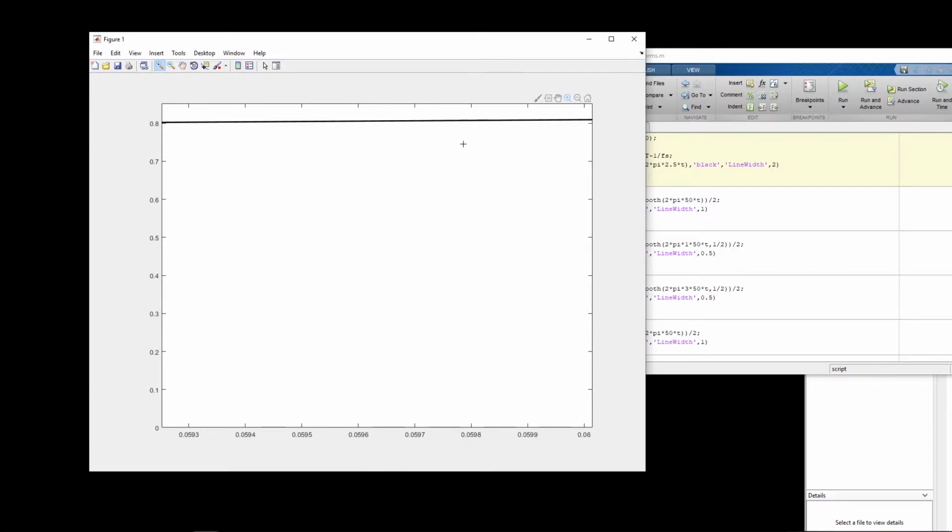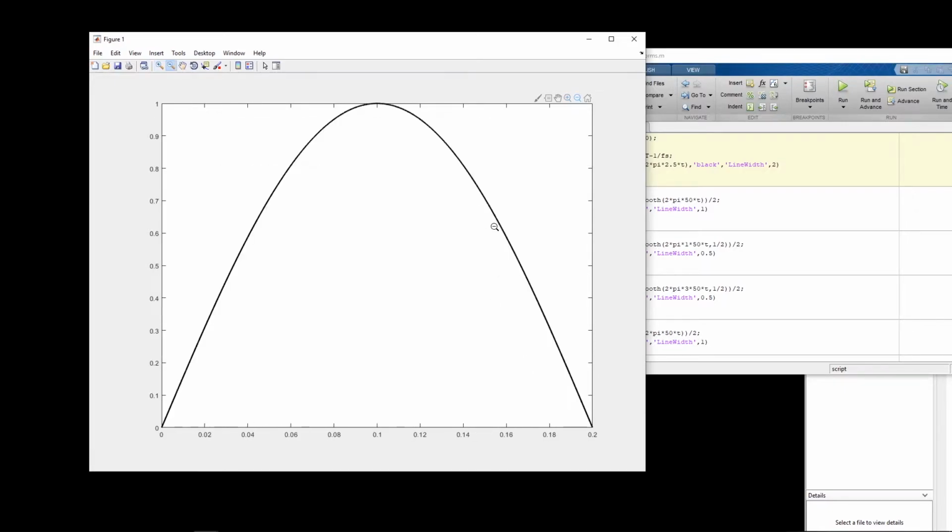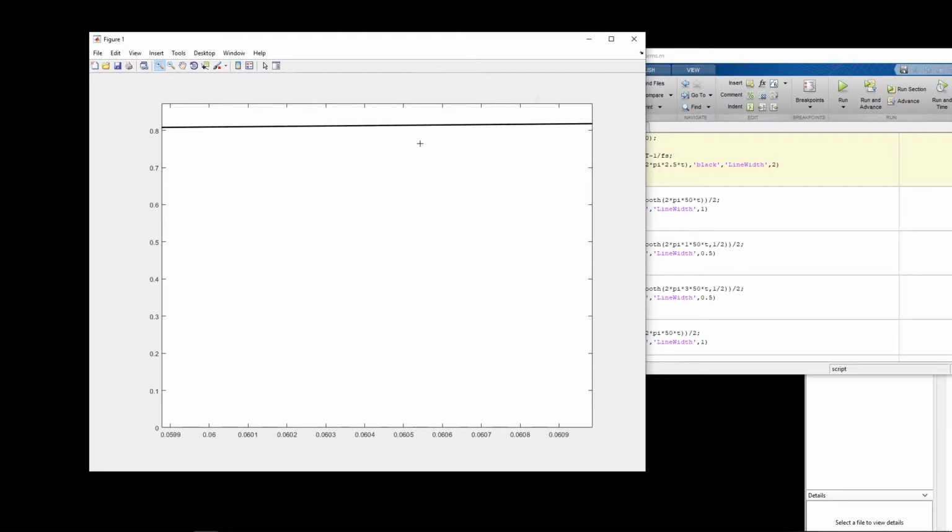So basically what I have to prove is that if I have a flat line at a certain magnitude, and if I use a triangular waveform or a sawtooth waveform, then the condition of the integral that I mentioned is true, because any main signal we can actually convert to small delta t steps, and then basically we put them next to each other and build the whole signal. So the proof that I'm going to show you is only for when the time step is very small and this signal is more or less flat. All right, so now let's see how to prove this.